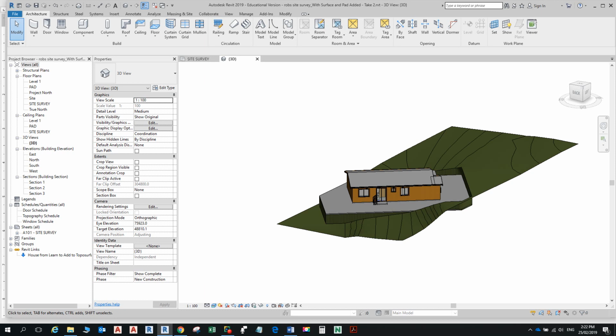We'll do another exercise where we'll show you how it would normally work, where you draw the house first and then you bring the site plan in at a different orientation. There's a number of ways of doing it, and it's fine to understand why it doesn't work. You could just rename those views. If they're working in reverse, you can just rename them to be the True North or the Project North, depending on what it should be.